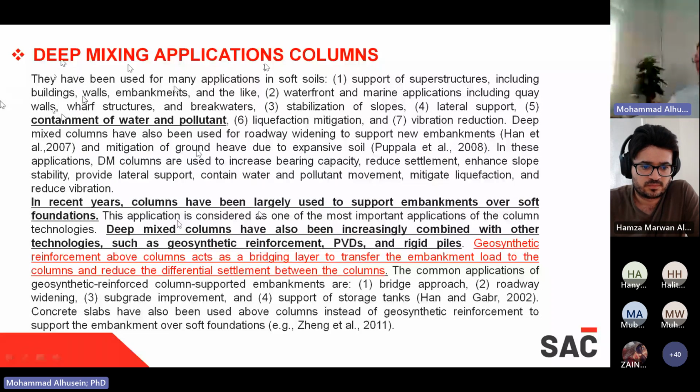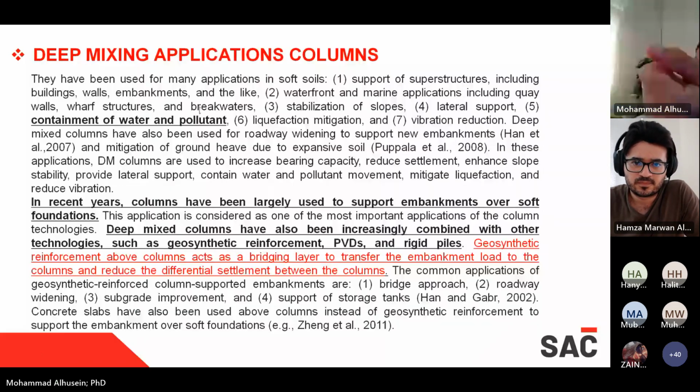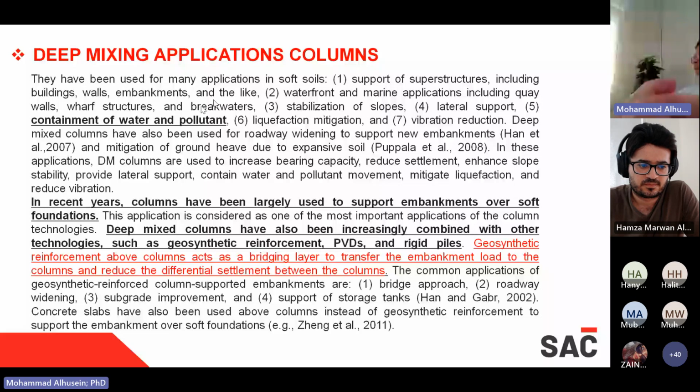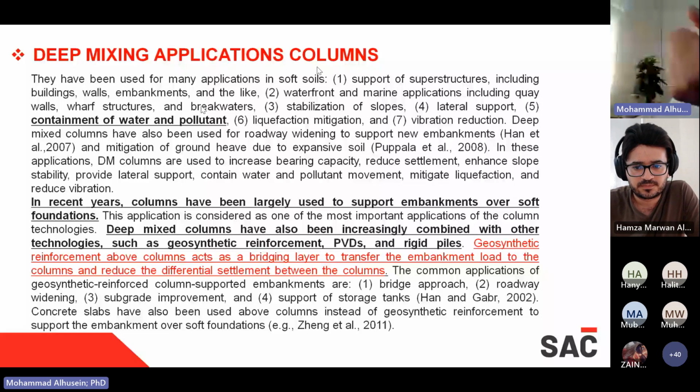Other normal techniques are not recommended at all for this kind of material, like dynamic compaction, dynamic replacement, rapid impact compaction, even vibro replacement, because in more than one site, all these techniques failed to safely support the structure, and the structure and infrastructure with time developed subsidence, cracks, collapse, etc.